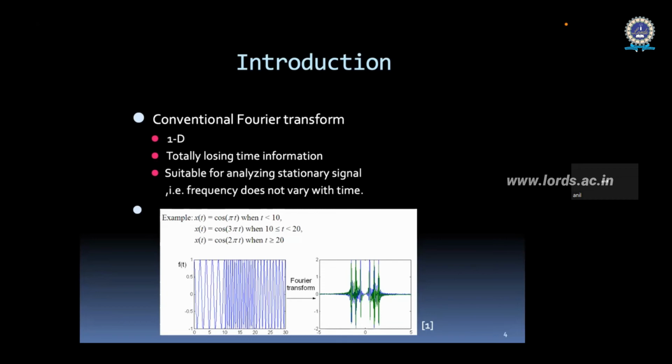That's why I have shown you the time scale modification, that means how to change the duration of the speech signal using short-term Fourier transform, which is called phase vocoder. Any of you who want to do a BTech project or work on it, just go for phase vocoder and try to see. I have created, let us say, an anger speech. Can you create a sad speech? Like that you can choose some topics.